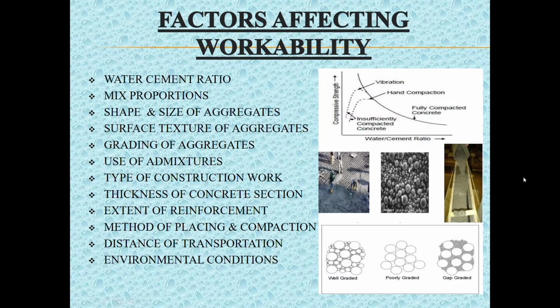Workability requirement of concrete varies with each type of construction work and compaction method used. For example, concrete which is considered workable for roof constructions cannot be considered workable for mass concrete foundations. Workability requirement when vibrators are used for constructions is different from when vibrators are not used.